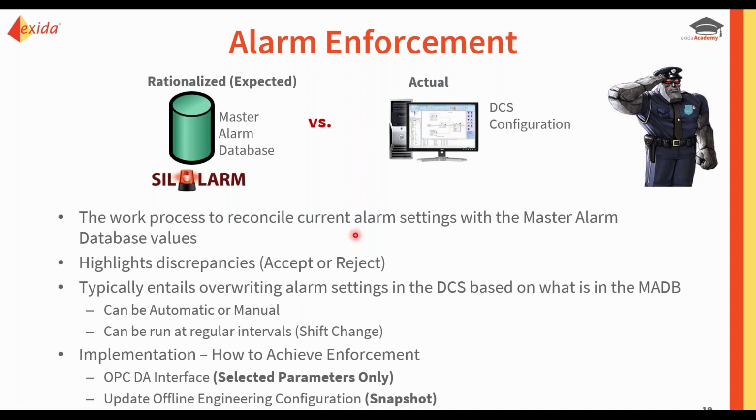So that enforcement action can take place automatically, it can take place manually, or it can also be run periodically, like at shift change. I know some end users that brag about their alarm systems and audit and enforcement capabilities and how they run their auditing and enforcement program at the end of every shift to reset the alarm settings back to where they're supposed to be.